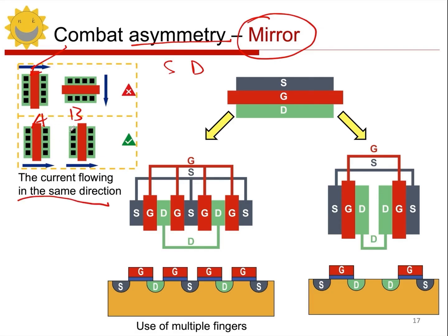Now let's take a look at how we can make the original leakage of a single transistor more consistent. Here, we can mainly use techniques like finger and multiplier to address this. First, let's talk about fingers, to make the original leakage more consistent.